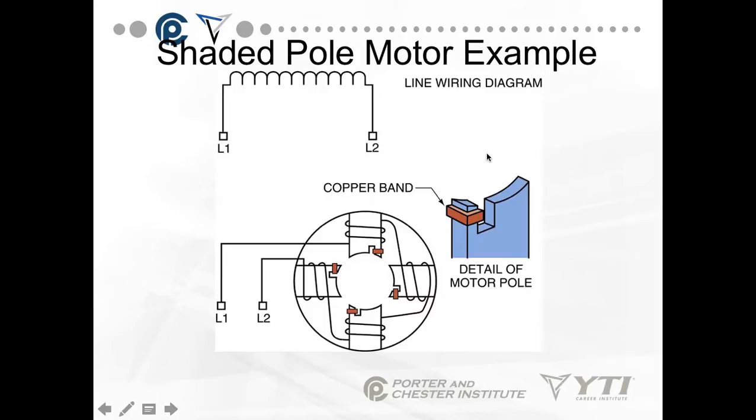So, again, motors have 2 parts we're really worried about. We have the stator, which is the non-movable part with all the windings. We have the rotor, which is the movable part with the magnets in the center. And the stator, when energized with alternating current, builds up a magnetic charge that actually forces those magnets on the rotor to continuously rotate so that north and north are never together. Start windings have way more wire than the run winding, and shaded pole motors only have a single winding, but they have a copper band that helps move the motor.